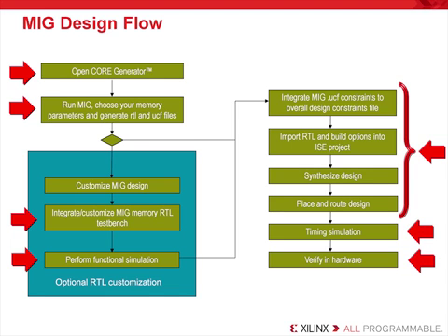After building it, you should always complete a behavioral simulation to verify that this controller meets your system needs, and of course this is supported. After you have decided that this controller is what you want, integrate your UCF file into the overall design's constraints file. Import your source RTL, synthesize, and finally place and route the design with the implementation tools. Note that timing simulation is still supported and encouraged, but it is not required. Lastly, verify your design in hardware, probably with one of our demo boards.